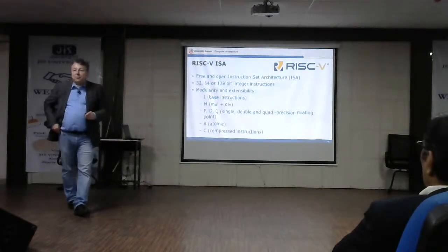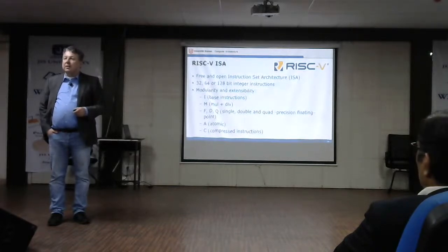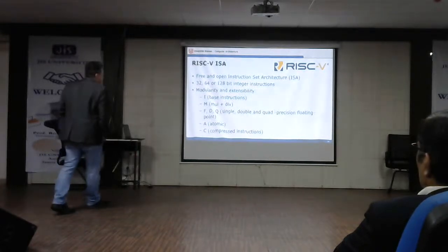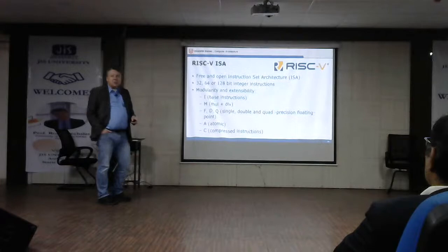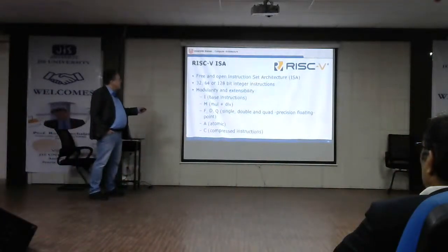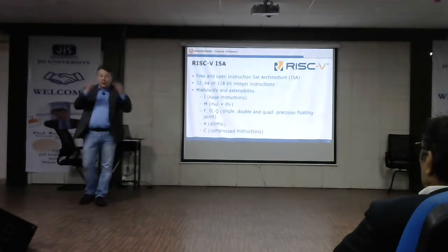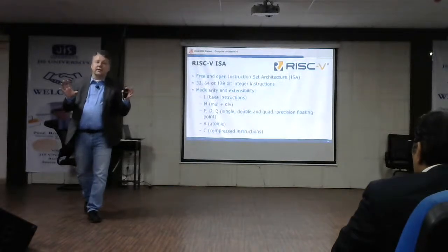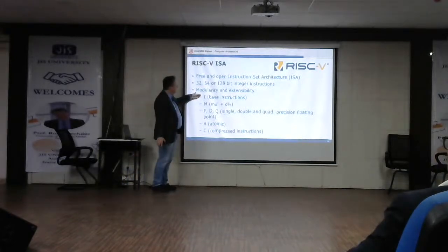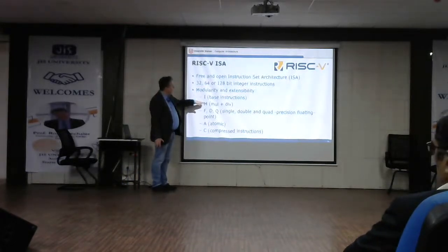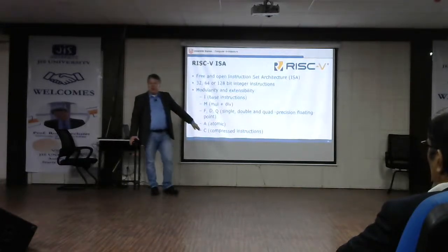An architecture that is very popular these days is the RISC-V. Maybe some of you have heard of that. It's a free and open instruction set architecture that comes with different bit widths of 32, 64, 128. And what makes it very interesting is this kind of modularity and extensibility. So you can generate this core in different sizes. That means you can have a very simple integer instruction-based architecture. You can also add some kind of arithmetic like multipliers. You can have floating point and so on.